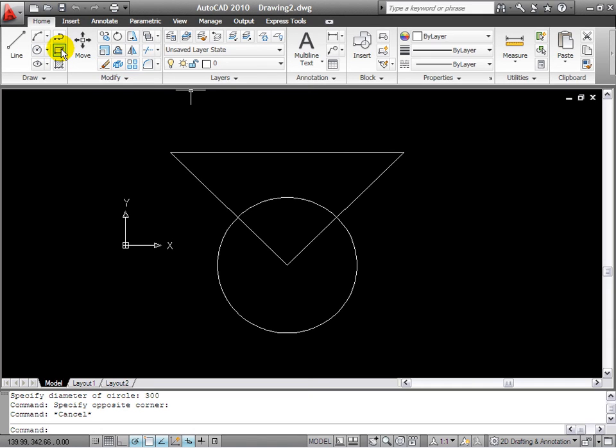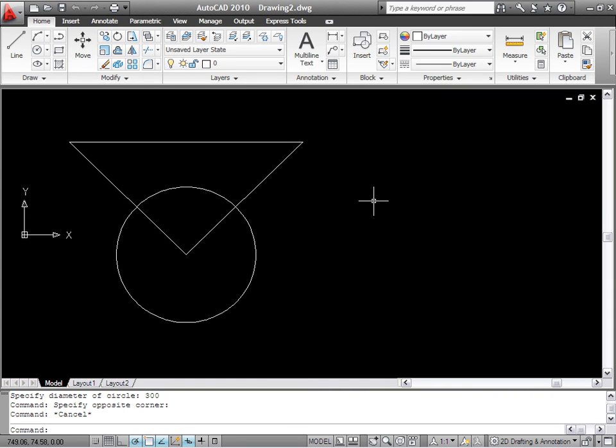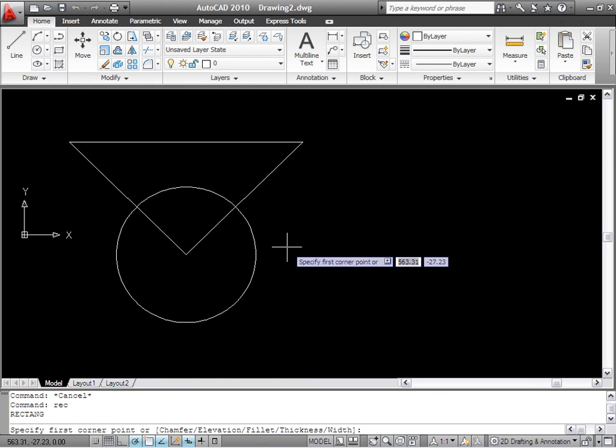How about rectangle? Rectangle command again follows REC, which is the first few alphabets of the word, just spacebar. Rectangle is to create polylines. Polylines is a continuous line object. We'll check it out now for rectangle.